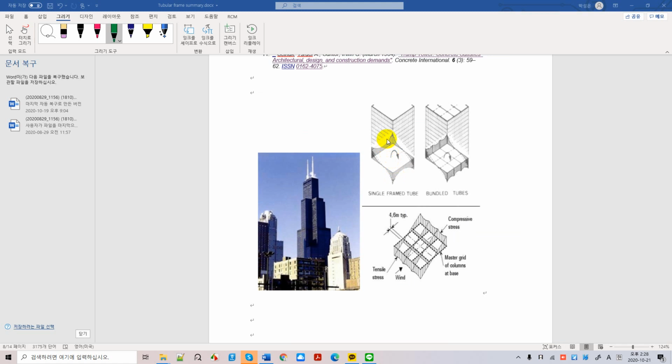Okay, this concludes that we have a serious shear lag phenomenon here, not linear, right? And we can put further interior frames that cross the building sections so that we can reduce the shear lag phenomenon. How? We can increase the spandrel beams' shear capacity as well. Also, we can provide a direct loading path from here to here.